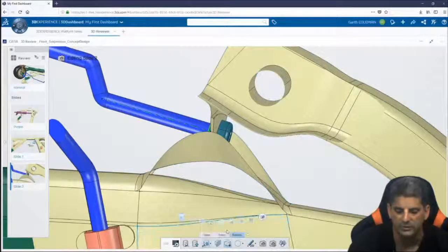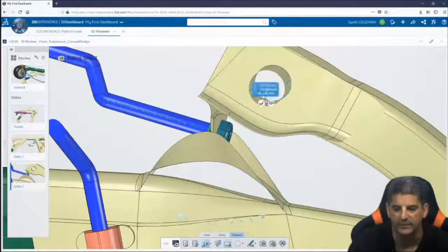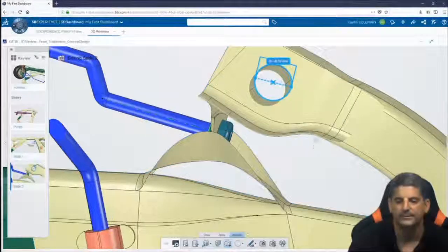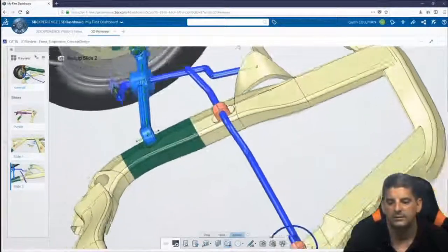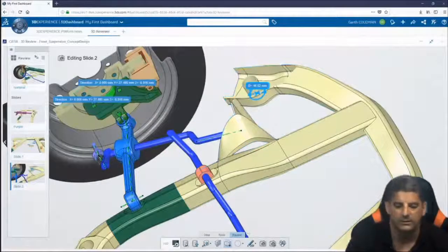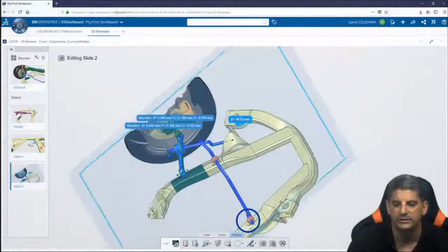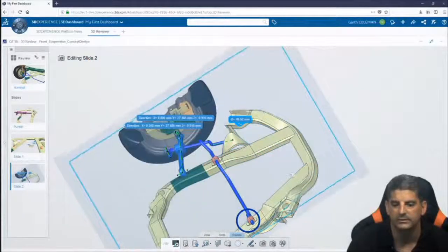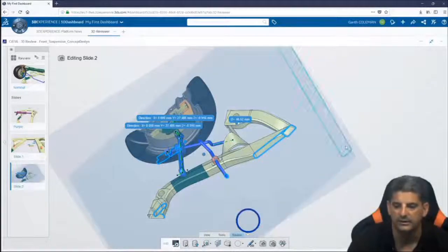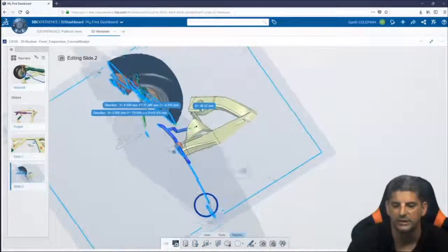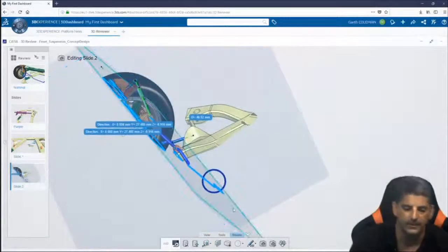And potentially now I can do a measurement. Maybe I can do an axis or circle. Or when I do my 3-point measurement, and maybe it'd be more accurate, because at least accurate in that particular plane. Now that's one click, second click, and I can decide what I want. In this case, I want a 3-point circle. There's my 3-point circle, okay? Now, if I grab the side of the section, this allows me to rotate it around. In fact, if I put a couple of sections on there, now I can do some pretty interesting quarter sections and things like that. Okay.